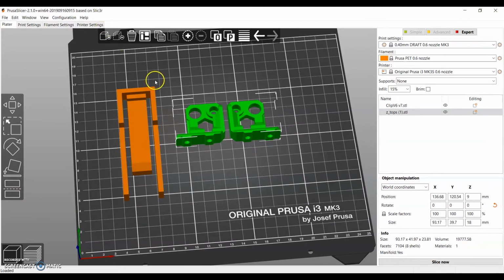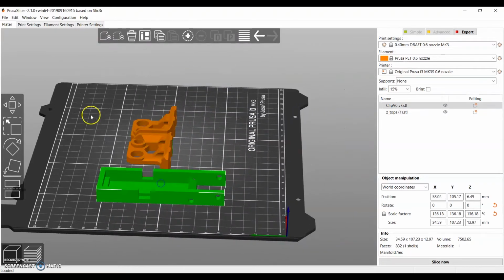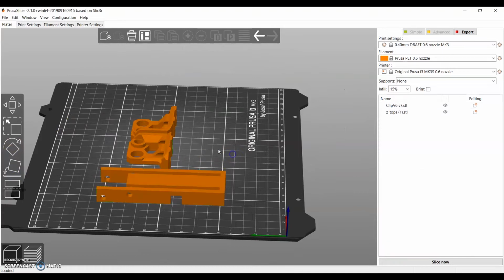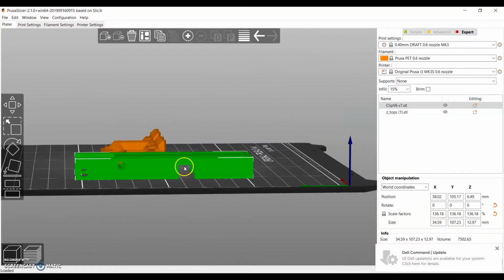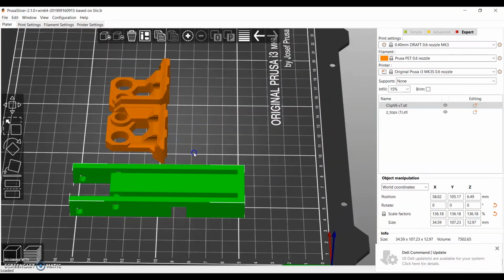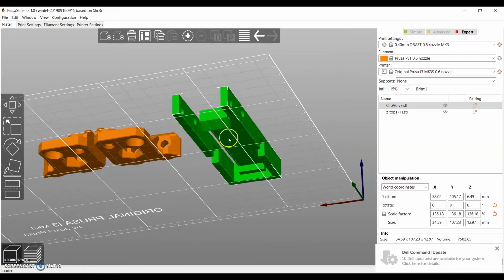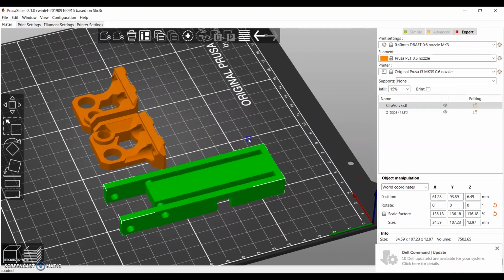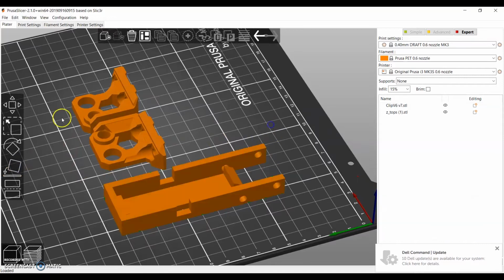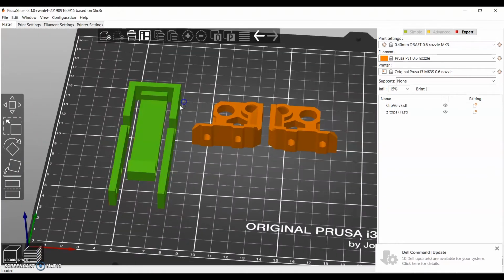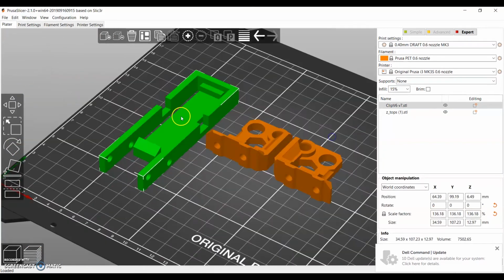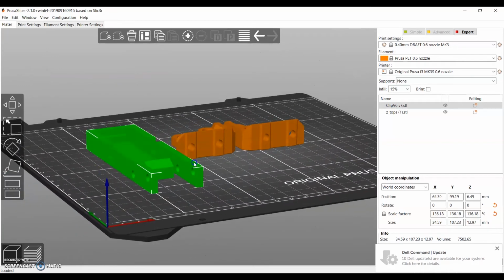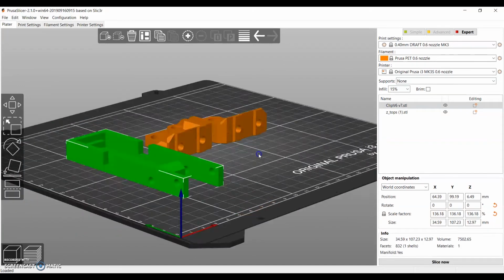Secondly, you want to orientate your part so that minimal supports are required. So coming back to this first model, if we flip it back around, you can see here there's some overhang right here that would require supports, as well as this part that is not touching the build plate. But if we flipped it over, you can see it's laying flat now. These don't need supports because there's no overhang anymore. This is touching the build plate, and then the holes, of course, will require supports.